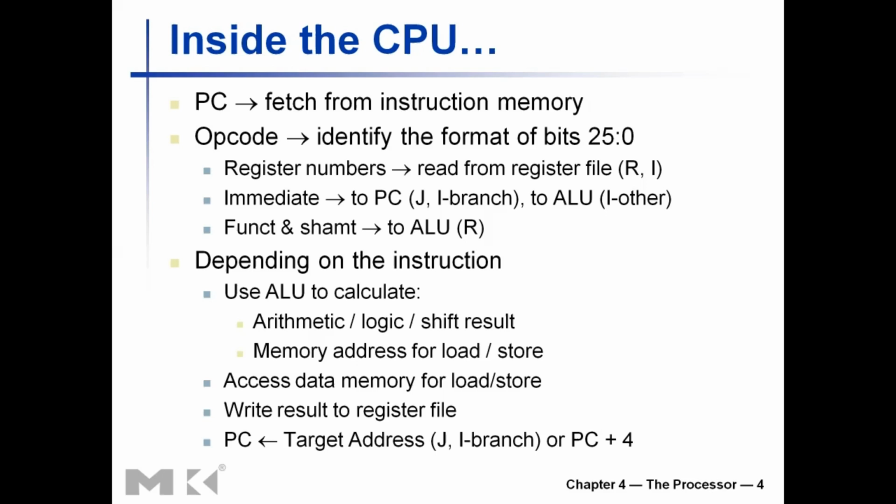Then if it is a load instruction, you will have something read from the memory which needs to be written into a register file. Or if it is an arithmetic or logic or shift type instruction, you need to write the result of the ALU into a register in the register file. So that is the next step, writing the result to a register file.